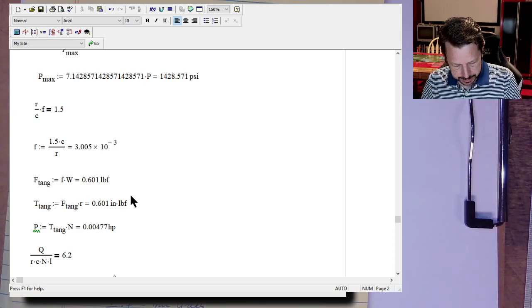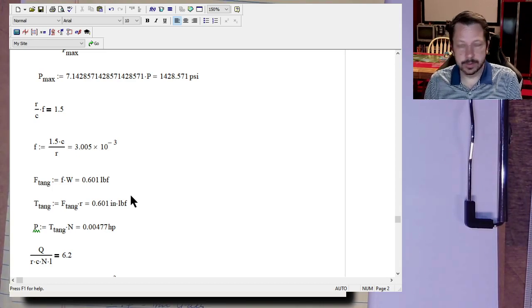It does talk about the idea of pressure fed bearings. So you might force lubricant into one of these bearings versus them just being submerged in lubricant, or having a different splash system for how the lubricant gets into the journal and the bushing in the first place. Talks about a couple of materials, and a couple more examples.